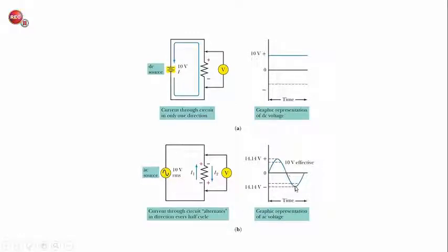And after the voltage reaches its maximum value, the voltage will again start to decrease, or I should say increase, because here it's negative, increasing back towards 0. And again at 0 volts, the current in the circuit will be 0. And this pattern repeats indefinitely as long as the source is connected to the circuit. We will continue to see these sine wave patterns of voltage and current in the circuit.